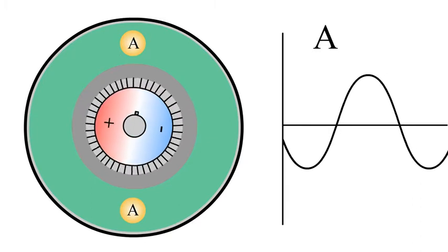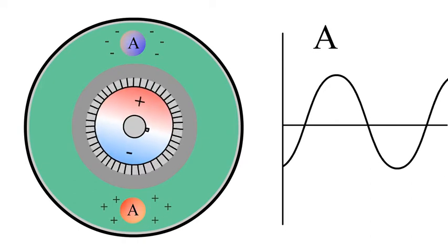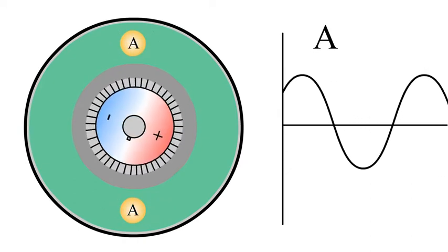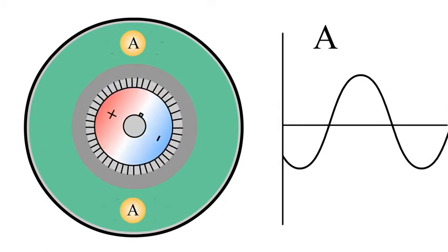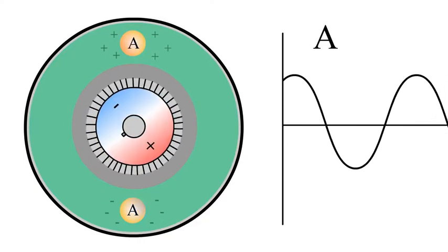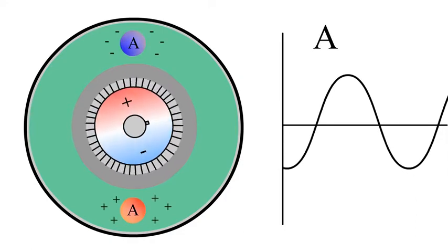When the negative side of the sine wave is strongest, the polarity inside the motor reverses, making the opposite windings positive and negative. The rotor in the center is magnetically charged as well, and it tries to align itself with the magnetic field being generated by the stator. But with only one phase going, it makes for a pretty choppy spin of the motor.